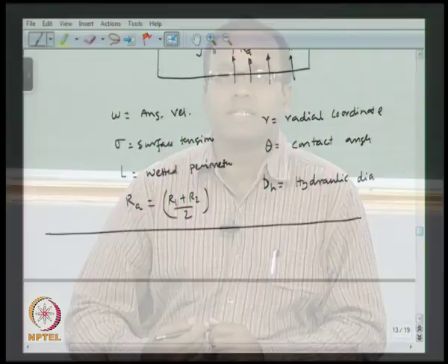So, with that let us discuss the ultrasonic micropump. Ultrasonic micropumps are the mechanical type micropumps, but they belong to the dynamic type micropumps. Okay. So, in case of the ultrasonic micropump we do not have any moving part. What we do is we have a thin membrane and we have transducers on the thin membrane coated with PZT materials, and these PZT materials are excited using the transducer. So, they generate what is called acoustic waves, okay. This is called flexural plate acoustic waves.